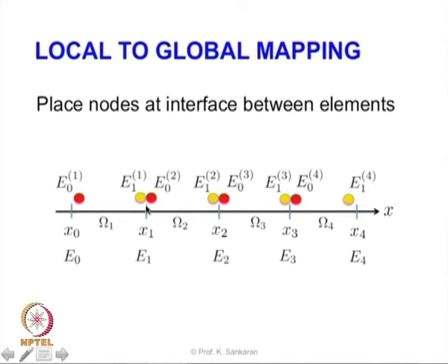The degrees of freedom is nothing but the points where we measure or assign the field quantities. So inside the physical element sigma 1 there are 2 points where we assign the field values. Those are exactly the end points of those elements.